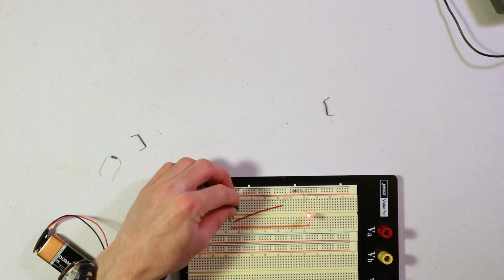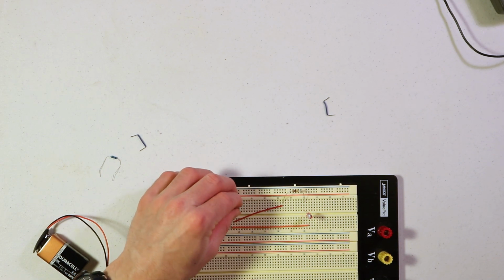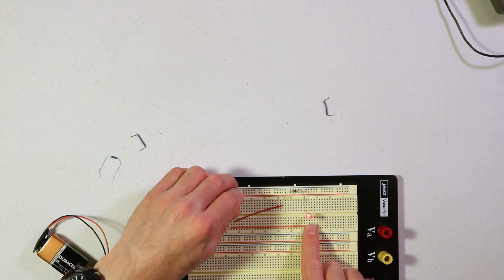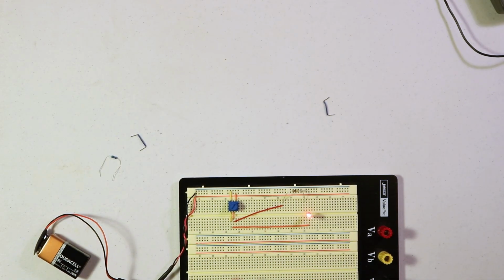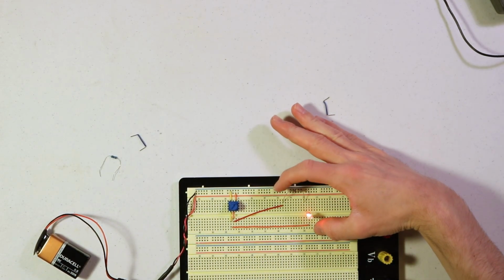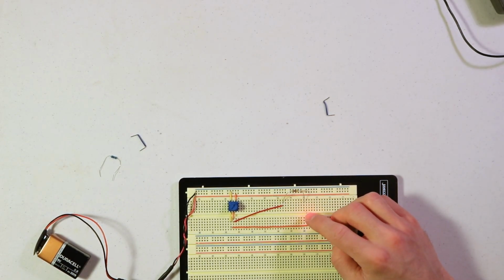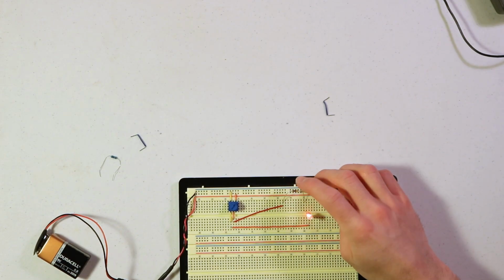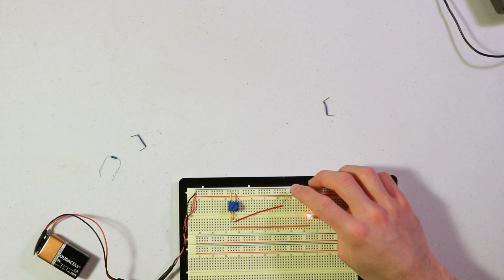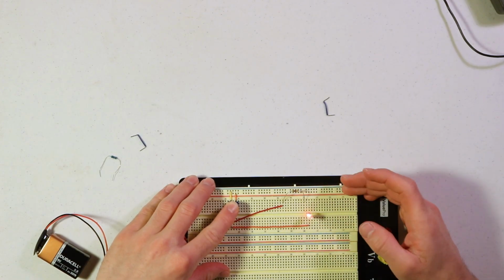And now, as we adjust the knob, we can control the voltage on our LED, which then also adjusts the brightness. Now, I did say earlier that the current is what controls the brightness of our LED, and that is still true in this case. I'm just adjusting how much voltage gets applied between this resistor and the LED, and the voltage on the LED is going to be somewhat constant, like it's going to just use a certain amount of voltage if it has that available. The remaining voltage is then going to be across our resistor, and so the resistor then is going to determine how much current flows. So by adjusting the voltage here, we actually are adjusting the current, which then controls the brightness of our LED.